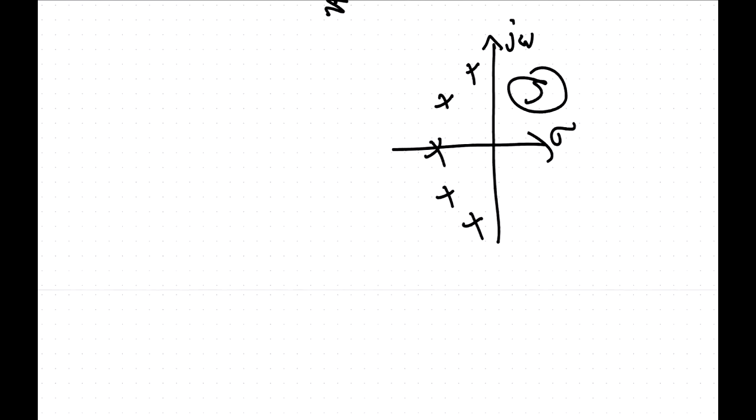I've seen a thing on, are you talking about the NMOS and PMOS pair, like only one of them turning on? Oh, but that's even worse then, because if only one of them is on and one of them is off, you're going to have more nonlinearity. But I've seen a thing in a textbook where there's some sort of feedback where when one of them turns on, it shunts some extra current to one of the other pairs so that it increases their transconductance.